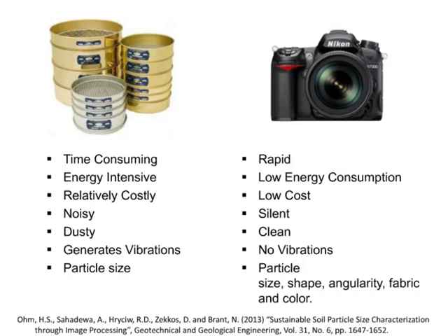I don't think I need to tell the current audience about all the problems that are associated with the sieve analysis test. You can read them here. They're expensive, time-consuming and energy-intensive, noisy, dusty, generate vibrations. By contrast, taking images with the camera and analyzing them is much faster, much less costly, clean, silent, modern. But most importantly, in addition to getting just the particle size distribution, we can get so much more information, including shape, angularity, fabric, and soil color.